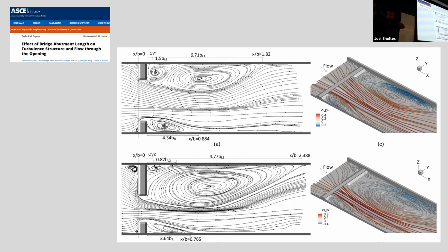So here's the fill that you would put into a river so that you would minimize the bridge span, right? It's cheaper and easier to put a bunch of dirt in, but you're constricting flow. So they're looking at how different types of abutments and ratios of river width to abutment or constriction width result in different kinds of hydraulics downstream.